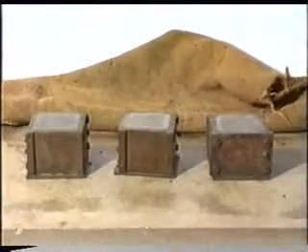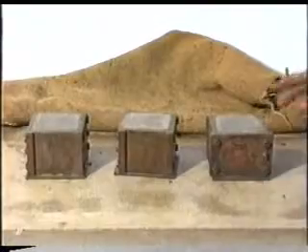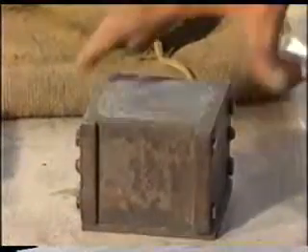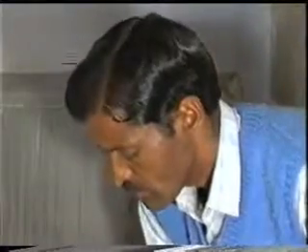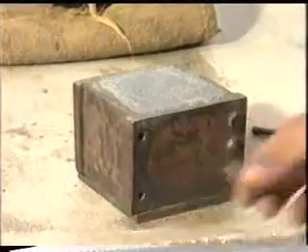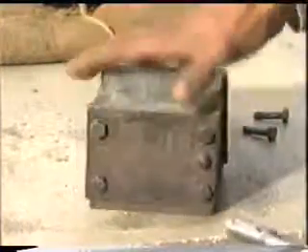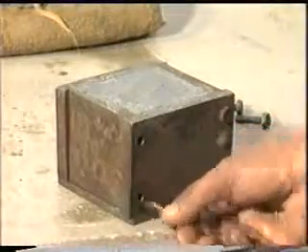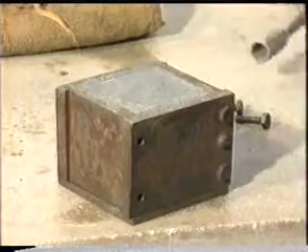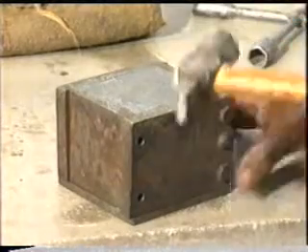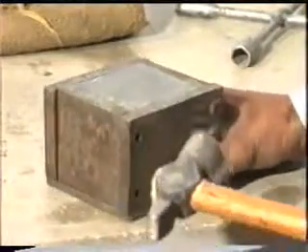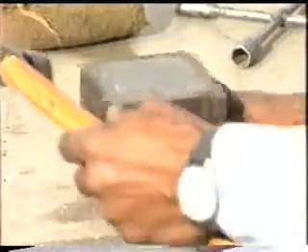At the end of 24 hours, the gunny bag is taken off. The mold is then dismantled to dislodge the cast cement cube. A gentle tap with the hammer on free ends helps in the easy removal of cube without damaging its ends.